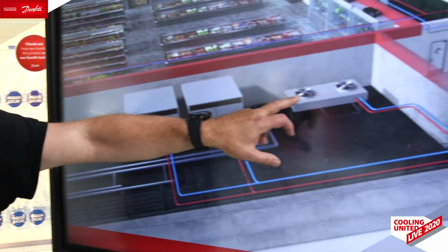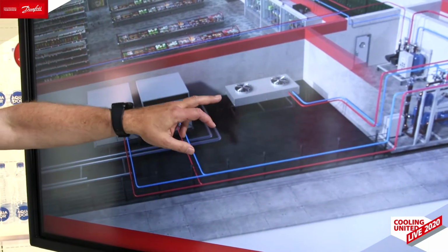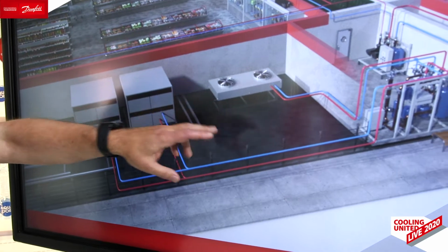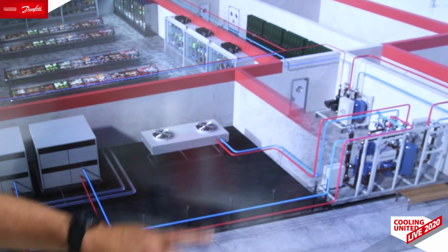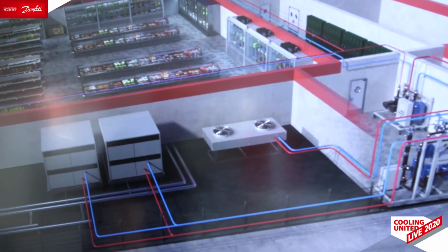At the lower temperature end, you need to have a pressure ratio of approximately 2. That means the condensing pressure has to be at least around 2 times the evaporating pressure. That could be a little bit challenging at low ambient, winter time, for example. Then you have to take some measures, like, for example, if you have a look again on the screen, if you slow down the speed of the fans, you can keep the temperature inside the system, or you can throttle the water flow through the condenser by using water valves like our WVO.